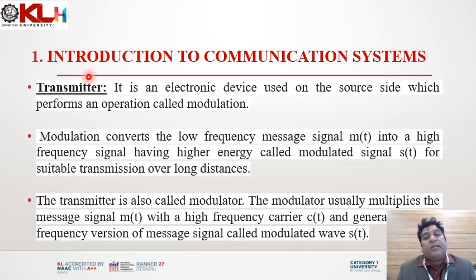Now the next block is the transmitter. This transmitter performs the operation called modulation. This modulation converts the message signal M of T, which is usually a low frequency voice signal, into a high frequency signal which will have higher energy, and this is called modulated wave, that can be transmitted over a large distance.